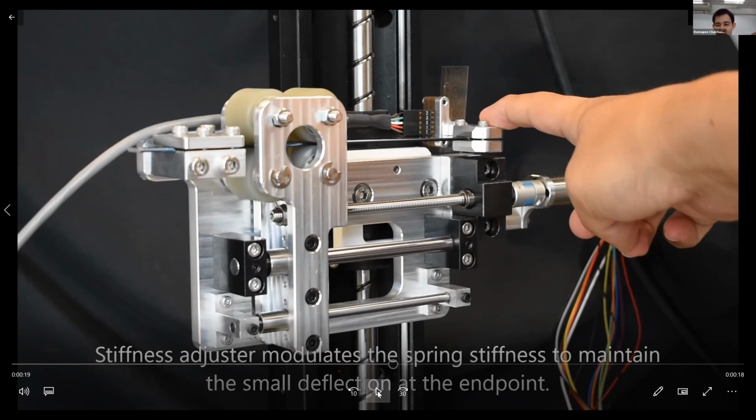And the important part of this system is the elastic component. The elastic component is the leaf spring. If you see my finger, I touch the robot at the end point, at the inertia, and the end point connects to one horizontal plate. That plate is made from spring steel sheet, and we select the stiffness for the spring steel sheet, and we can model the stiffness at the endpoint.